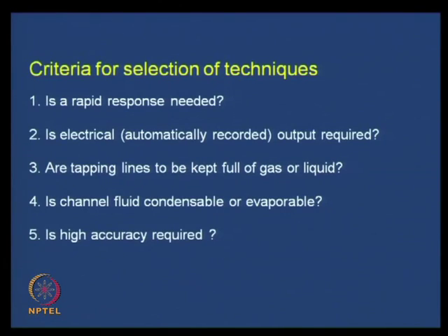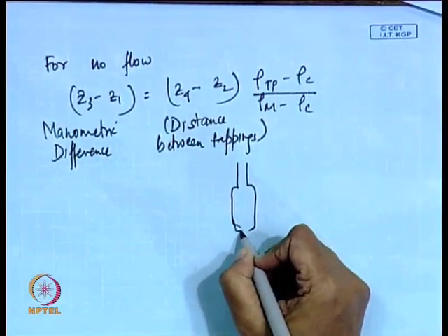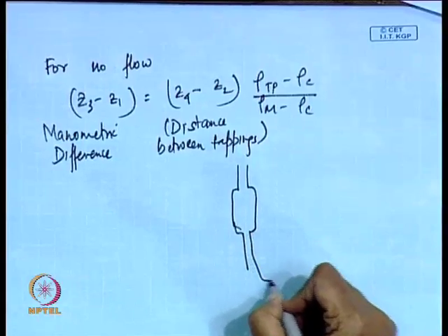Another thing which you already know from your single phase, I would just like to remind you: when we use manometers, the manometric liquid can enter the pressure line. How do we alleviate that particular problem? If you draw the diagram of a manometer which is usually supplied to you, I do not know whether you have ever noticed or thought why the manometer is made in this particular way.